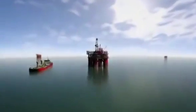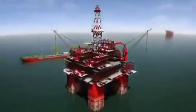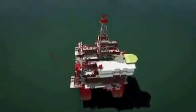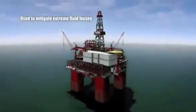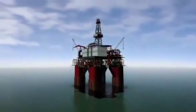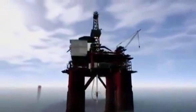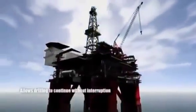Pressurized mudcap drilling is one of the 4 variations of managed pressure drilling, or MPD, recognized by the International Association of Drilling Contractors. Pressurized mudcap drilling is used to mitigate extreme fluid losses, commonly found in highly depleted and naturally fractured formations. In these extreme situations, where lost circulation techniques don't work or are too expensive, pressurized mudcap drilling allows drilling to continue without interruption.